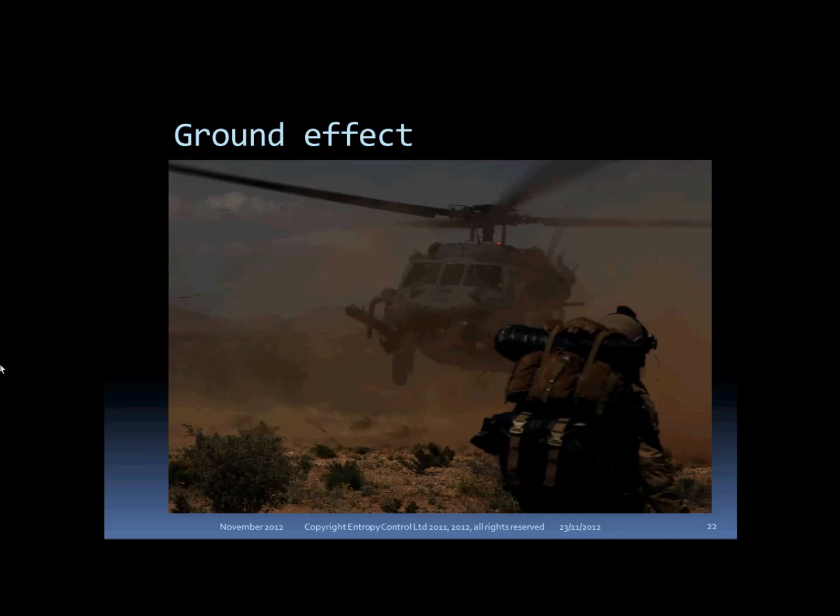And then there is ground effect. What happens to all that air that we throw down? Does it continue downward forever? No, it eventually reacts against the ground, causing a local rise in pressure. In the case of this helicopter, it's easy to imagine that if you populated each square foot of the ground underneath it with thousands of pressure gauges and added up all the pressures times areas for the area under the helicopter, it would add up to the weight of the helicopter itself, which is in fact true.